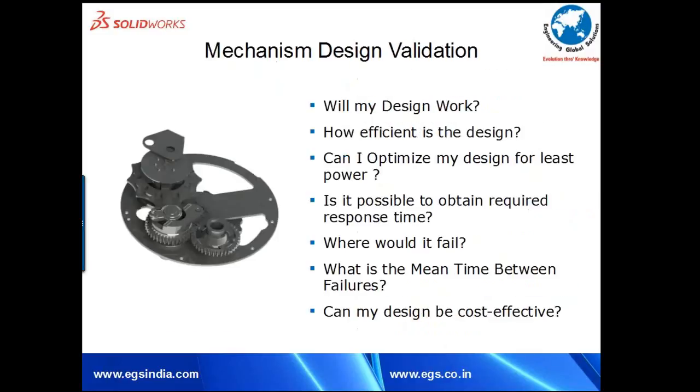Again, design for life. Similarly, for mechanism validation, we are looking at whether the design will work, the transmissibility of forces, the mean time between failures, and the cost-effective designs. When we are looking at all these different aspects, it is very important that we look at the fatigue life of the units more importantly than the factor of safety calculations.